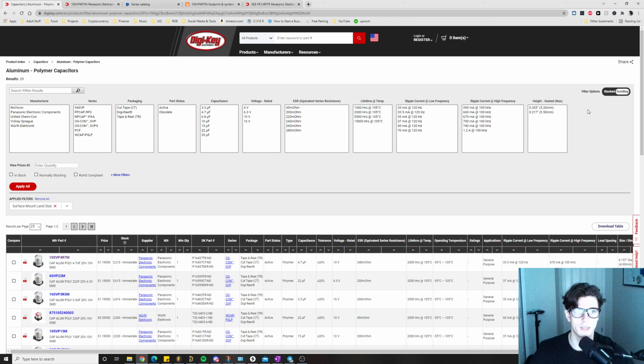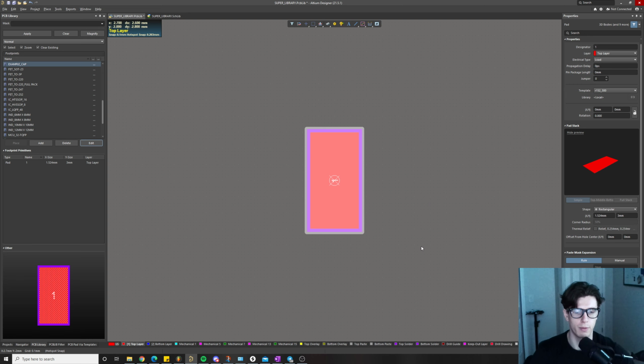Worth Electronic, right? A bunch of different companies make their own capacitors, and so we want to create a footprint that can fit all of these. They could have some slight variation. I'm not saying we have to make a huge component pad, like 6 millimeters by 8 millimeters, to fit all of them. No, it's just a slight amount of variation here. So that's why I'm adding 0.5 millimeter here, 0.5 millimeter there. It's okay. It won't hurt anything.